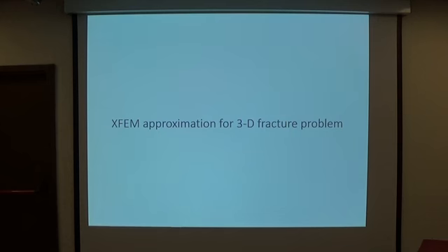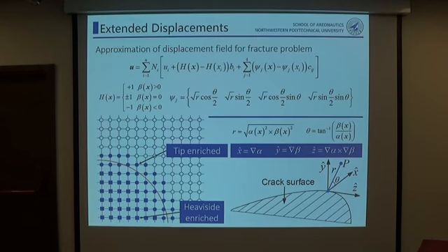Next, I will introduce the XFEM approximation for the fracture problem. This is a well-known displacement approximation for the fracture problem. Here H is the Heaviside enrichment function, which is constant on each side of the crack surface. And phi is the enrichment functions to simulate the asymptotic field near the crack front. And r and theta are defined in the local system.